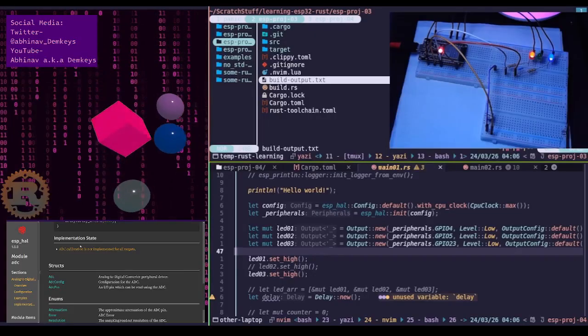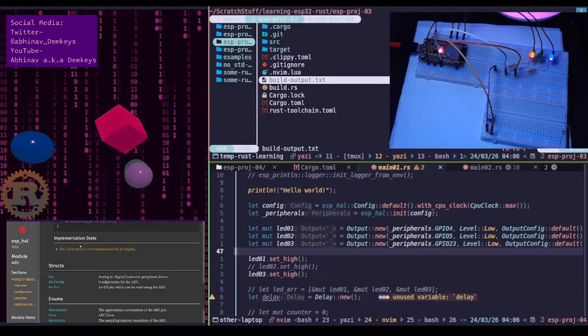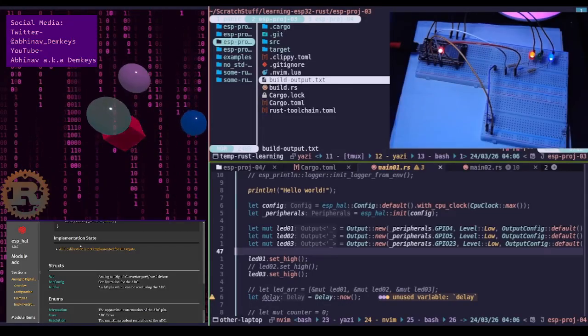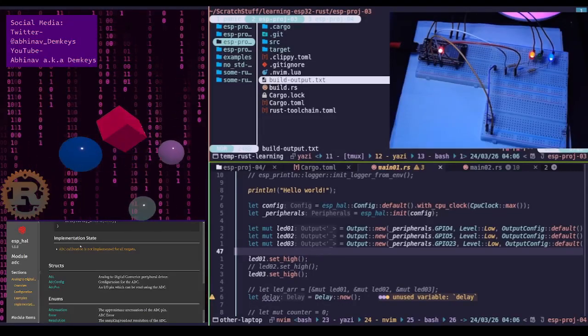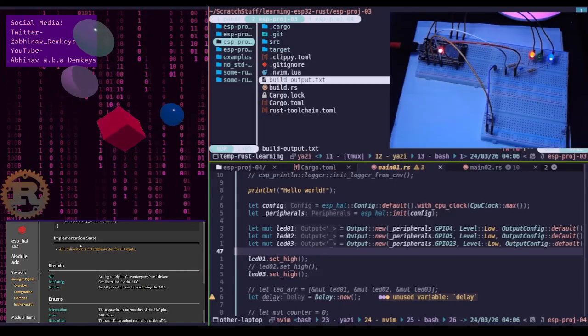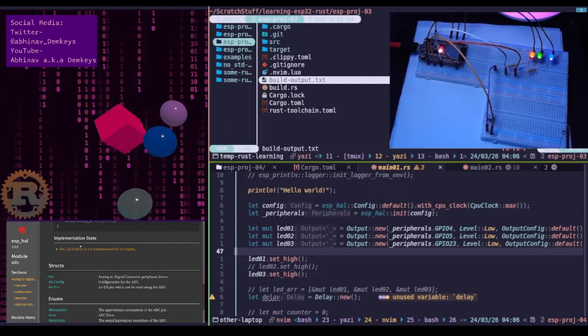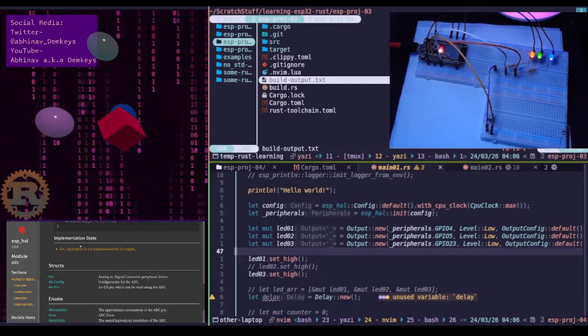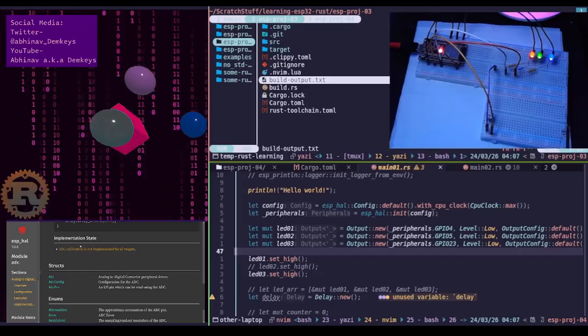You've got it exactly right. That is the formula for a straight line. The reason we use it for an ADC is that in an ideal world, the relationship between voltage or input and the digital number is a perfectly straight line. Okay, in an ideal world.